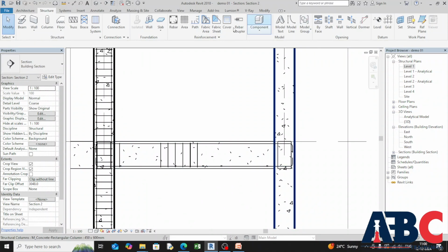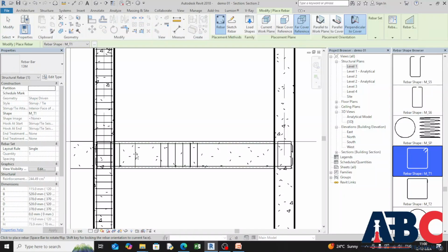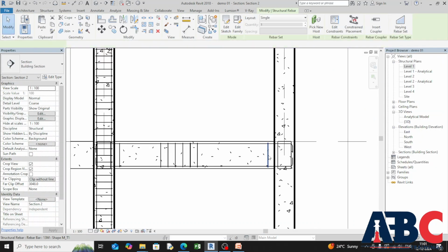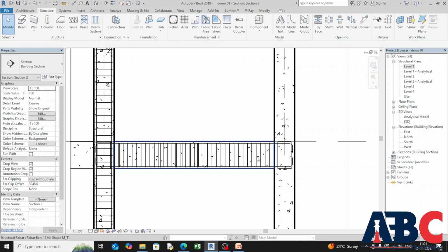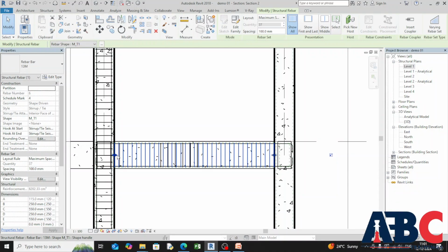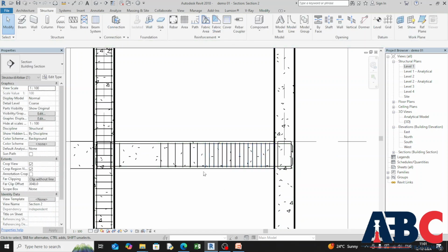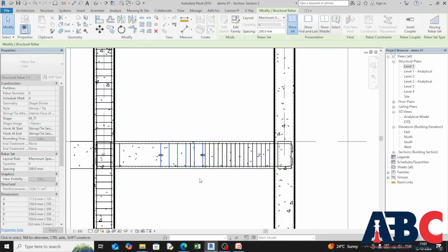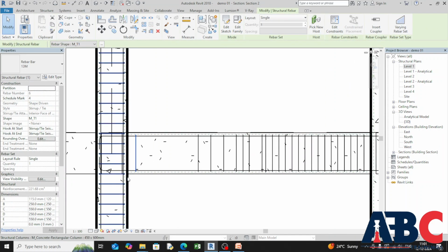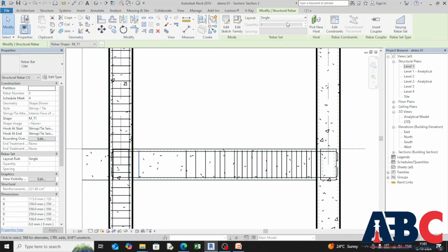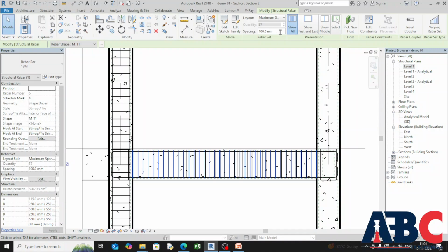And you want to create, so we have to go to the rebar again. We want to give 100 spacing at the start. So we will go to maximum spacing and 100. Click once here. You can edit it like that, just put it up to here. So we have provided 100 spacing up to this point also, the start point. For that, click here and maximum spacing 100.